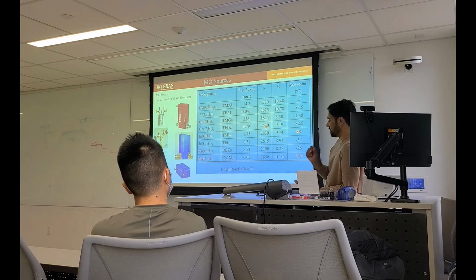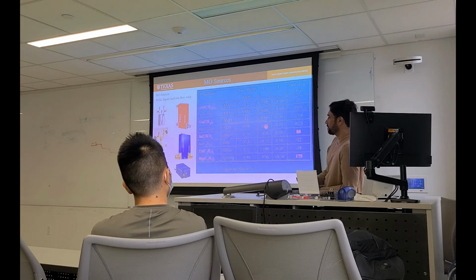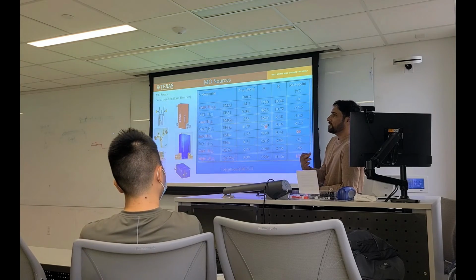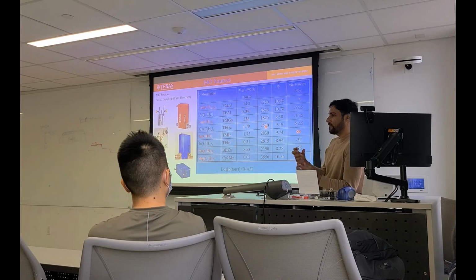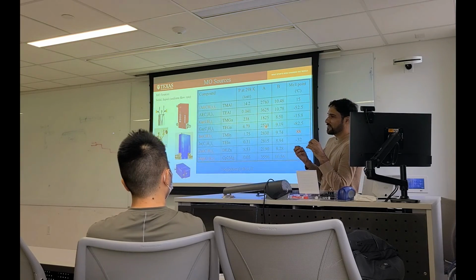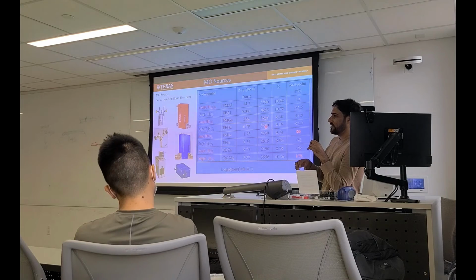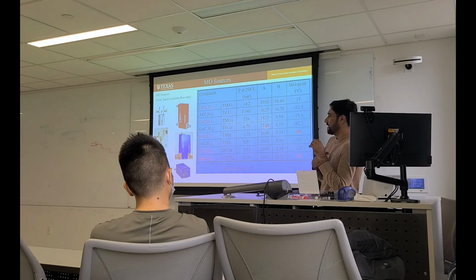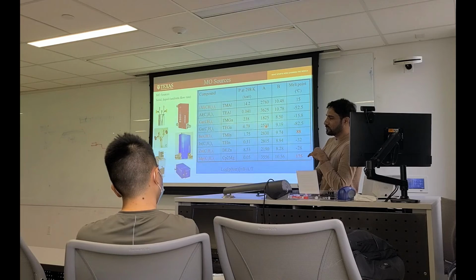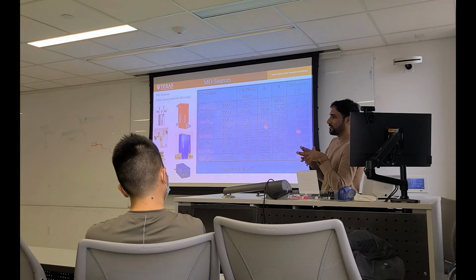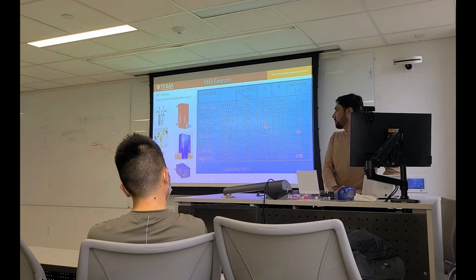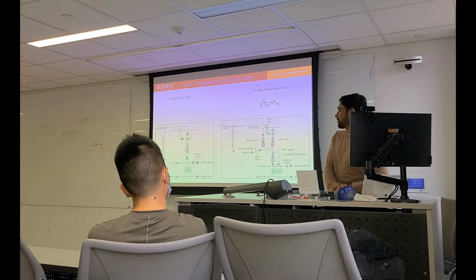Then there are other things also, like trimethyl gallium. It breaks in the vapor phase. That means its gallium radical is very reactive, and when it mixes with oxygen, which is also very reactive, it makes crystal before reaching the substrate. So that can create defects in your substrate. Triethyl gallium is not giving a very active gallium radical in the vapor phase. It will move to the substrate, and then oxygen can go and make the oxide. That's why we need to think about fundamentals. If you don't know the fundamentals, you will have problems.